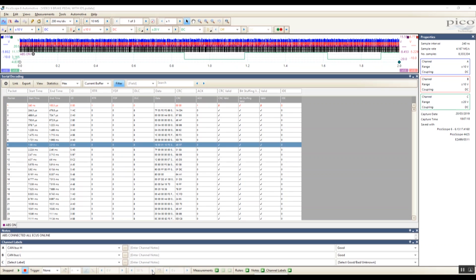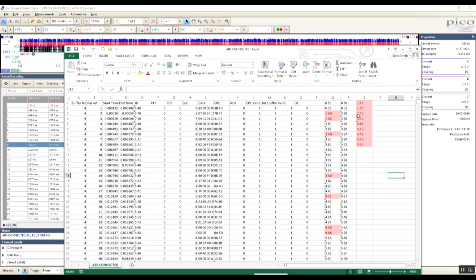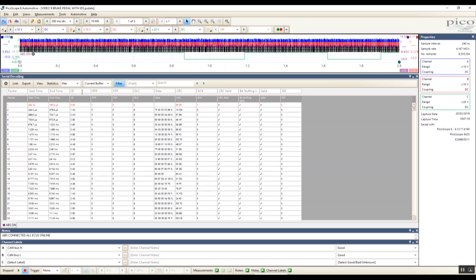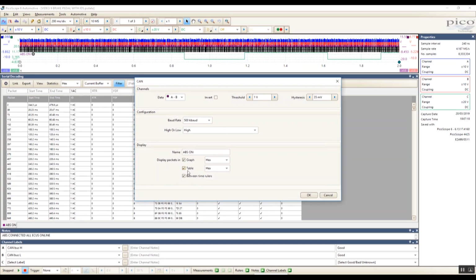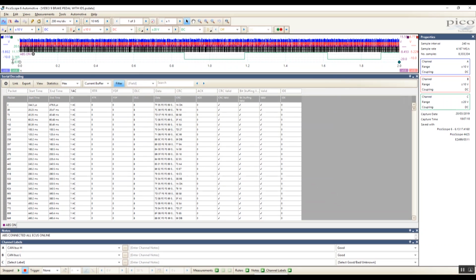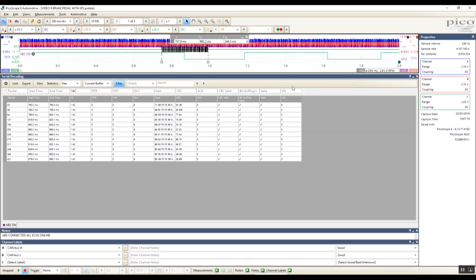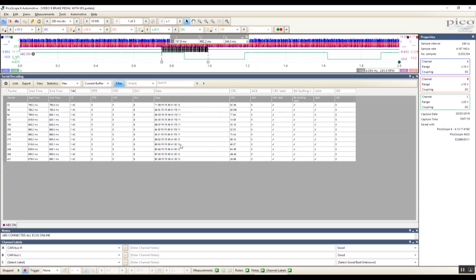So our next ID to filter on would be 1AC. So let's take a look at that. Filter 1AC. There we are, they're all listed there. But we're only interested in what happened here when the brake pedal went on. So let's just decode between the rulers. Let's go from here and here. Okay, so 1AC seems to have activity regardless. Let's just come back here.